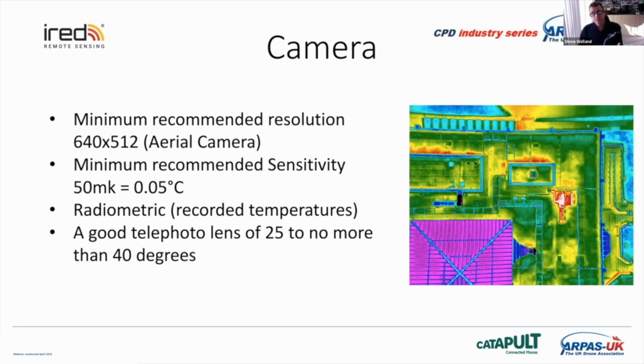So if you've got a 40-degree lens, for example, in the search and rescue world at 50 meters, you'll see twice the field of view than you would if you had 25 degrees. Now, if you're in the inspection world, we lose half the radiation. So this image you can see here, we would then lose important radiation that could be moisture ingress by choosing a wider lens.